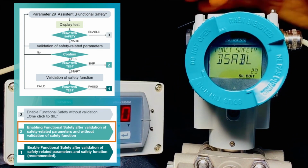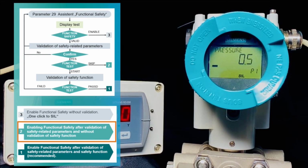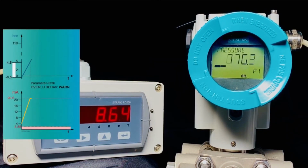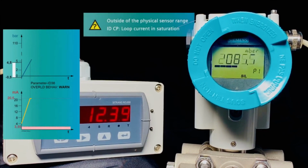We switch to the measurement view with the left arrow button. The SIL symbol appears on the display. As before, we increase the pressure and the NE107 symbol triangle with question mark appears. Under info appears CP, the output current is in saturation.